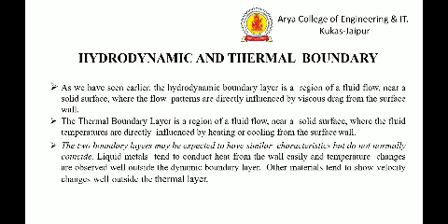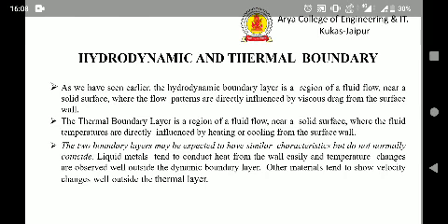The two boundary layers may be expected to have similar characteristics but do not normally coincide. Liquid metal tends to conduct heat from the wall easily, and temperature changes are observed well outside the dynamic boundary layer. Other materials tend to show velocity changes well outside the thermal boundary layer.